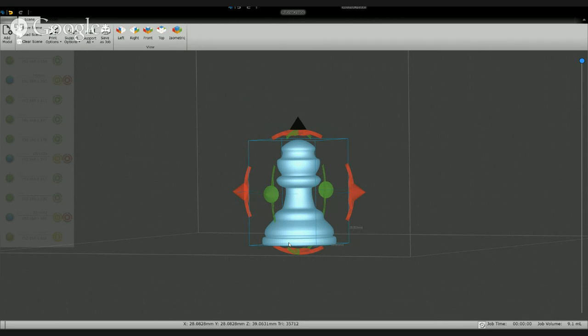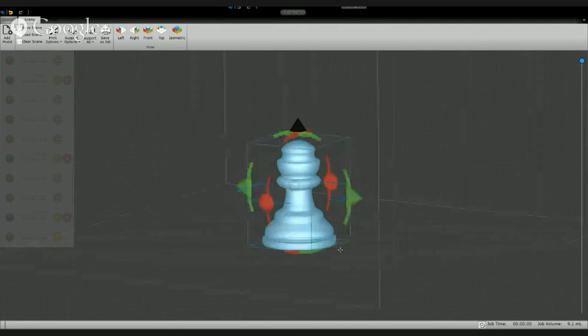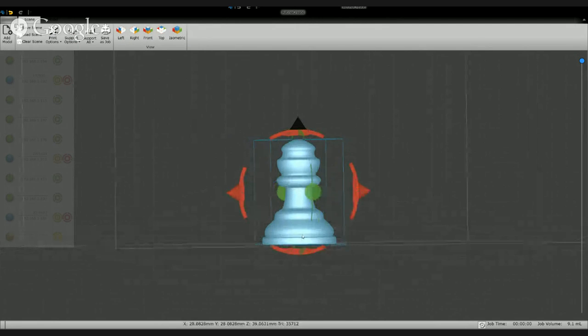There can be a little bit of a gap, or it can be pressed into the PDMS layer, depending on how you set the motor homing on your machine. So if you print things directly on the build plate, that's fine, but be aware that your Z accuracy will be off by as much as maybe 0.5 millimeter, depending on your motor homing.